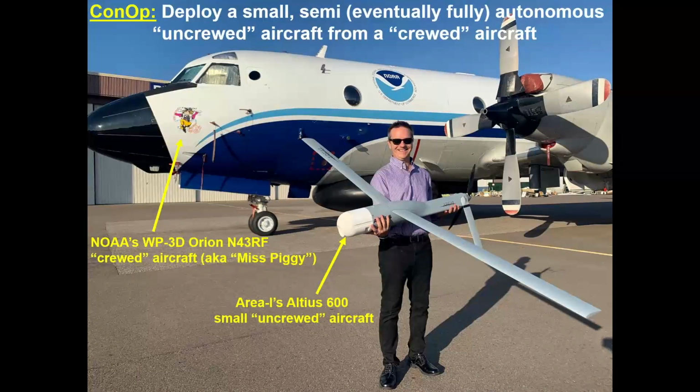It's a lot longer, the 9-foot wingspan. It has a stubby mode, which is half that wingspan, and we did fly in stubby mode, so we've actually never flown in this fully configured mode. It was a technical issue why we didn't, but in the end it probably was smart. With that amount of turbulence, we might not have done well with this extra long wingspan. It's about 27 pounds, so roughly the size of the Aerosonde. It's about twice the weight of the Coyote, but this thing can fly between 3 and 4 hours, which is much longer than we've ever had the capability.